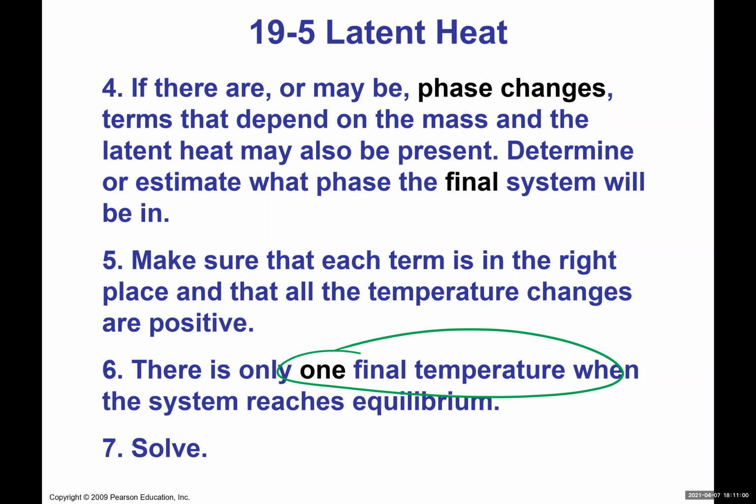So latent heat of vaporization is relevant for evaporation as well as boiling, right? Because that's basically happening at 100 degrees Celsius. Or you think like this, it's 100 degrees Celsius for water. I want to make sure that it's clear. It's for water. If you have, let's say, ethyl alcohol, then it's different temperatures, right? So for them, it's not 100 degrees that's relevant. For ethyl alcohol, the boiling point is 78 degrees Celsius. Okay, at 78 degrees Celsius, it evaporates. So that means you have to understand what type of substance you're dealing with.